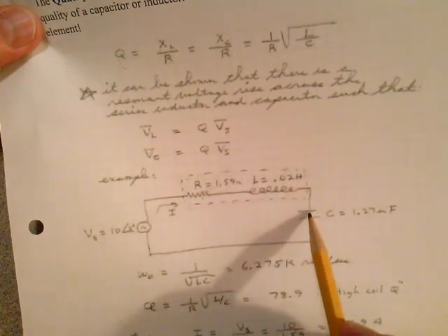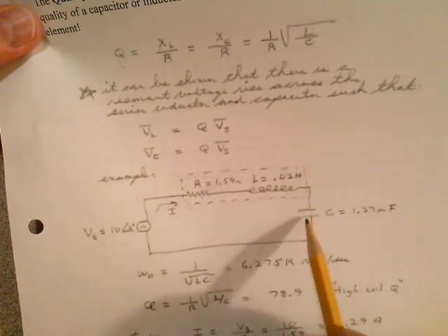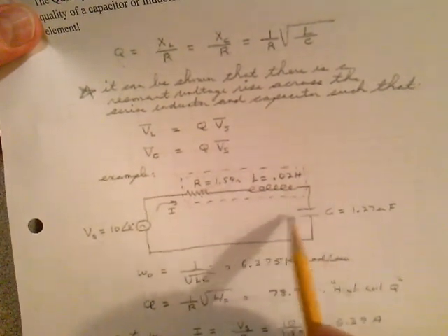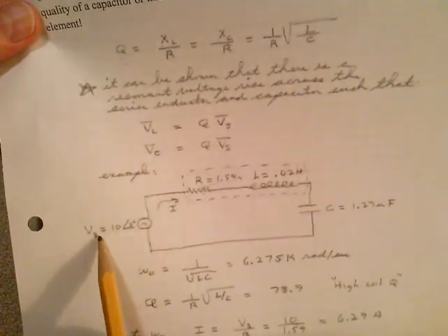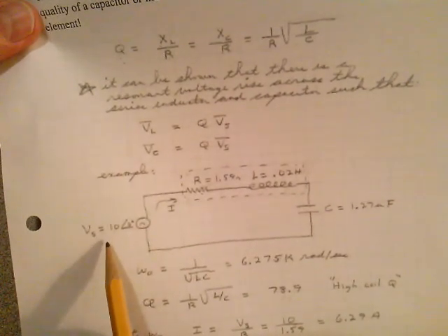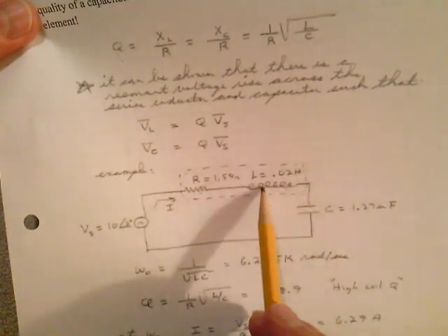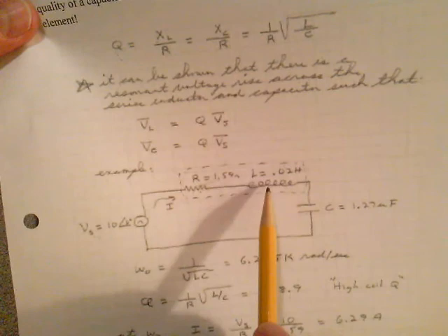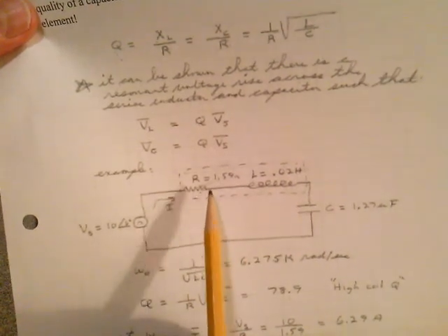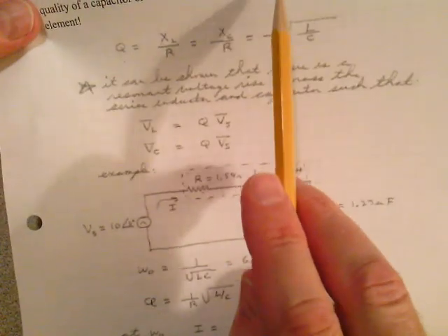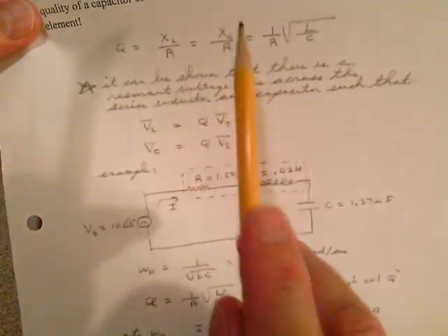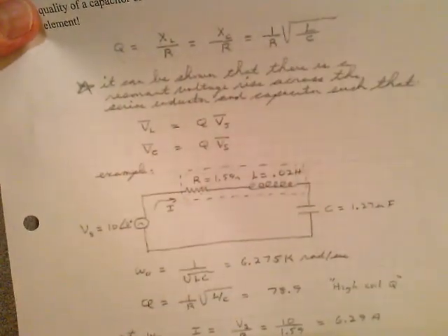Current doesn't actually flow through that dielectric. That's why we're not looking at that real high leakage resistance we talked about before. This is an AC circuit, don't forget. In an AC circuit, the only thing we're concerned about is where the current actually flows through, and it flows through that resistance here. So I just pull out that resistance, and it turns out that the smaller the value of R, obviously, the better the coil, and the higher the Q value.